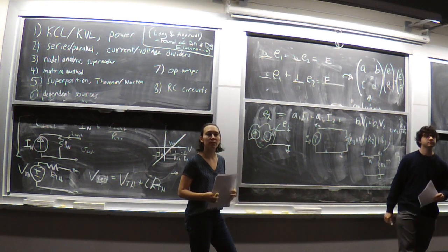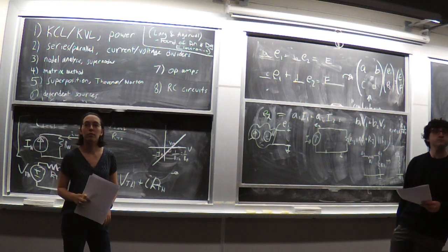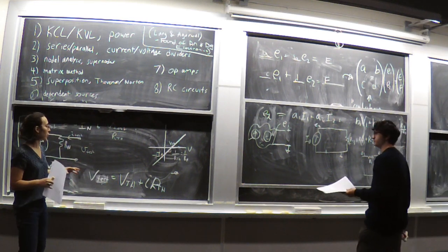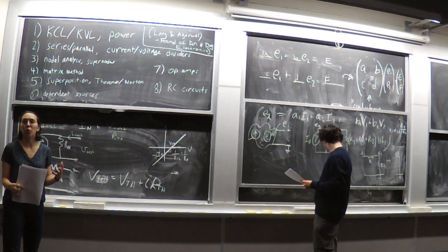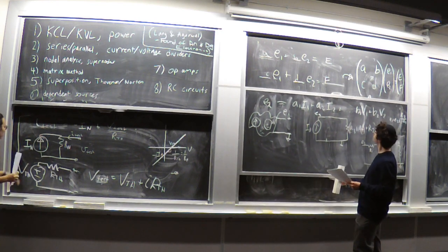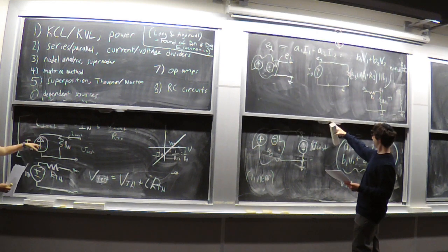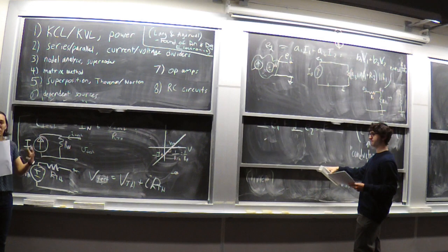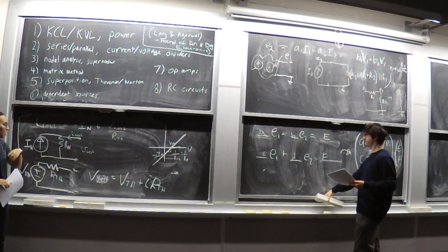If we switch from Thevenin to Norton, how do we know which way the current is flowing? Yeah, so going back to what Jacob was talking about and reinforcing in the beginning, it's all just the normal way of defining it. The way we've defined the Norton equivalent circuit is the Norton current goes this way, and again, with how we defined how we look at a device with the plus terminal, minus terminal, and current going into the device, that's the same thing here.